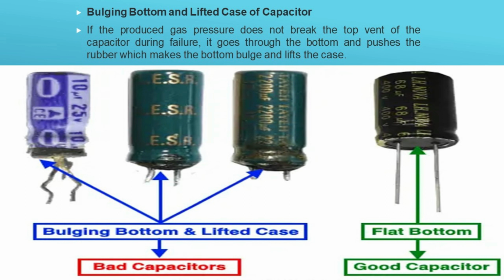Method 6. Test the capacitor by continuity test mode. In the DMM and AVO meter, the continuity test mode can also be used to check whether the capacitor is good, open or short. To do so, follow the simple instructions below. Disconnect the power supply and remove the capacitor from the circuit board.